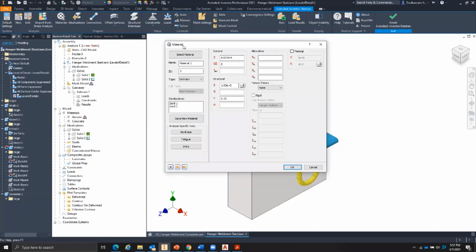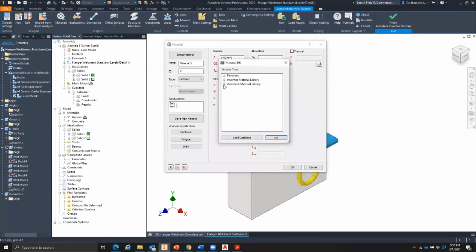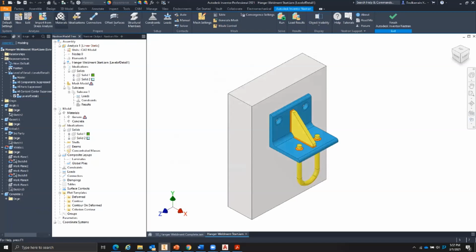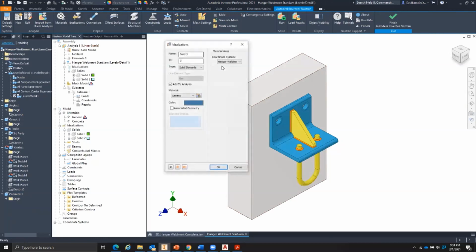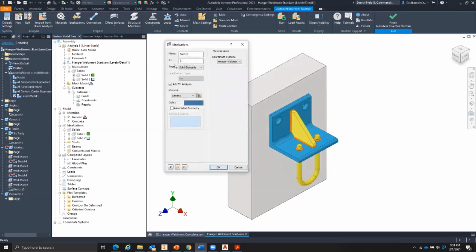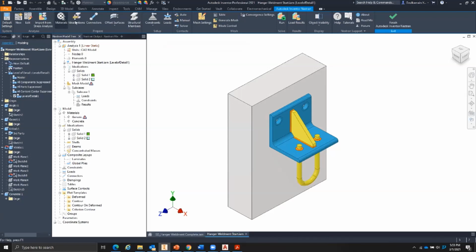In this case, we have a material browser here. Let's say I can set what is the material that I want to use during this simulation. Let me just close this first. If I did not assign materials, then later on, whenever I want to use idealization here, this is all the materials that are available to me, and I need to reassign again. I like to do it earlier. In case I do it here, it's already on this tab. That's why I say I like to start from the left hand side here and go to the right.